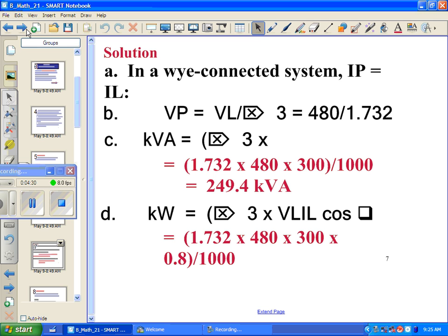All right. And then part B of this question. Oh, the currents are the same. Why are we dropping out? Don't do that. Got to fix that. That's good. So anyway, the first question was, what was the line current, I think, and we had the phase current. The second question is, what was the phase voltage? And we found that's 277.